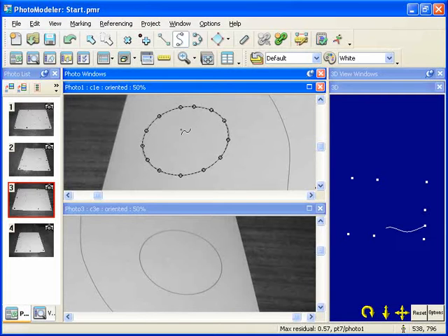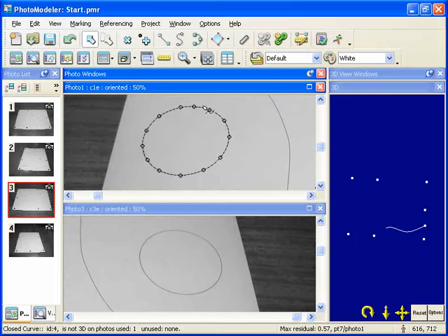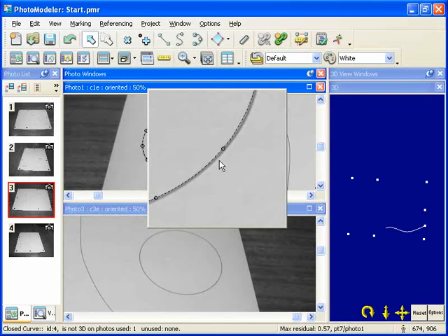One thing you might find with closed curves is that when they close, the 2D curve redraws, and you have to review to ensure it still lines up with the photo. You can modify a curve by going into Select Mode and clicking on one of the curve points and dragging to change its shape. We can study the curve more closely by using the Alt Zoom to move along the curve and study each part to see how well the mark matches the photographic curve.